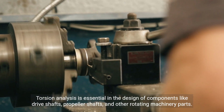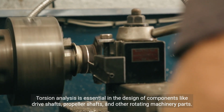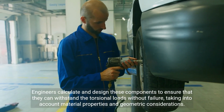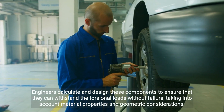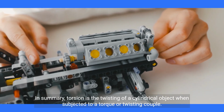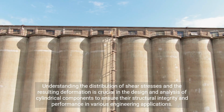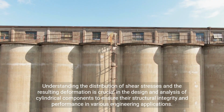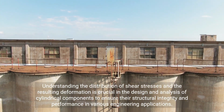Torsion analysis is essential in the design of components like drive shafts, propeller shafts, and other rotating machinery parts. Engineers calculate and design these components to ensure that they can withstand the torsional loads without failure, taking into account material properties and geometric considerations. In summary, torsion is the twisting of a cylindrical object when subjected to a torque or twisting couple. Understanding the distribution of shear stresses and the resulting deformation is crucial in the design and analysis of cylindrical components to ensure their structural integrity and performance in various engineering applications.